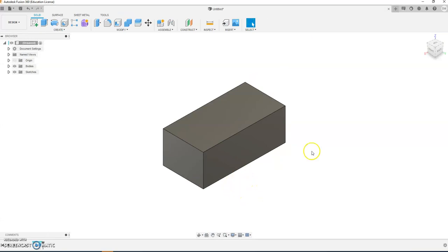All right, so what we're going to do now is we're going to put a notch in this drawing. Now, here's one thing that's a thing with AutoCAD, or sorry, with Fusion and Inventor both. Keeping your sketches as simple as possible is good. Making a really complex sketch that has 20, 30, 40, 100 dimensions in it is not good. It's just not good for the performance of your parts and all that. It's better to make simple sketches and simple extrusions.